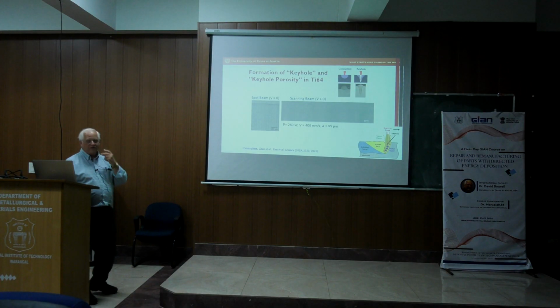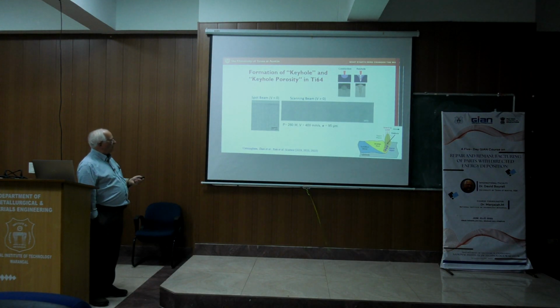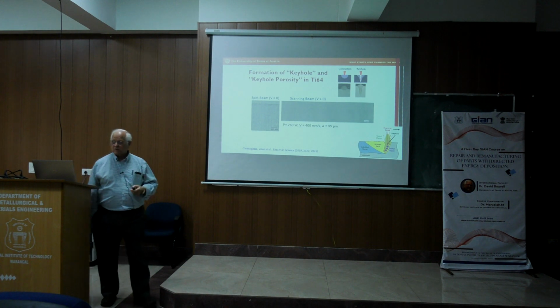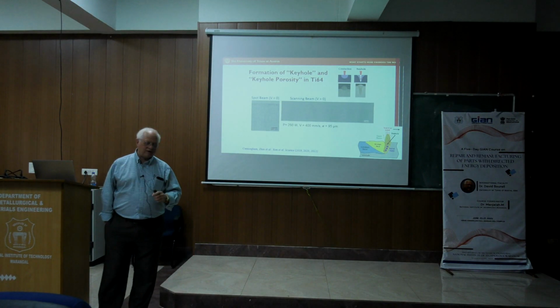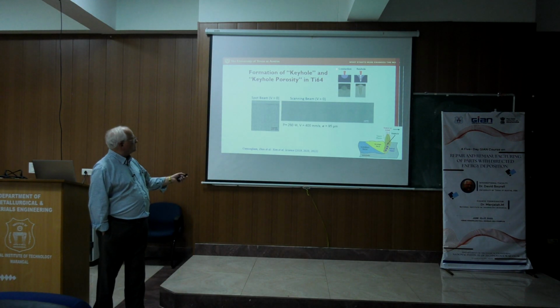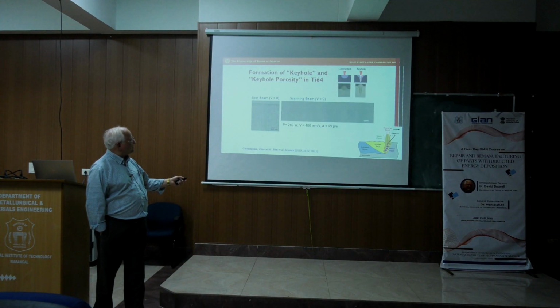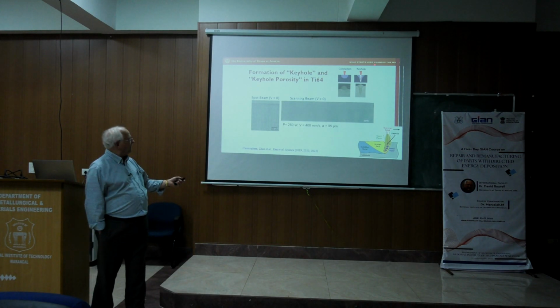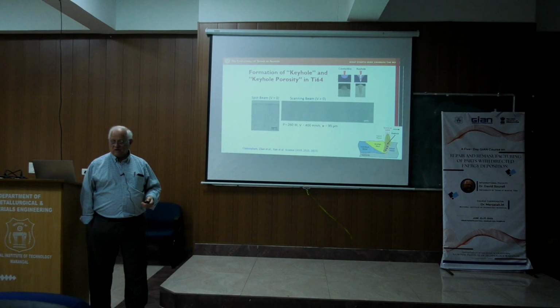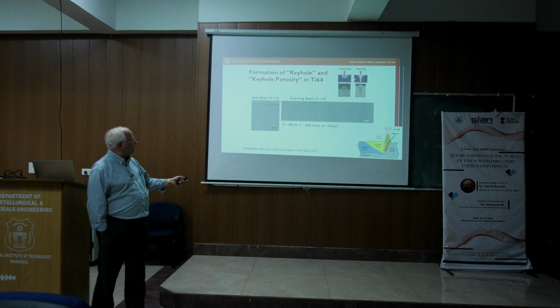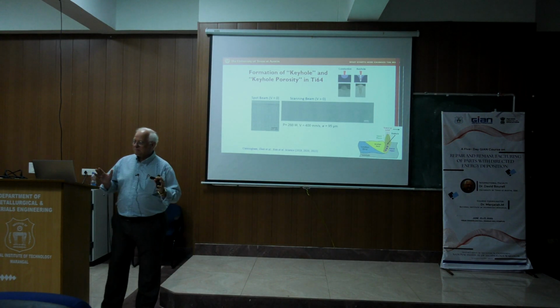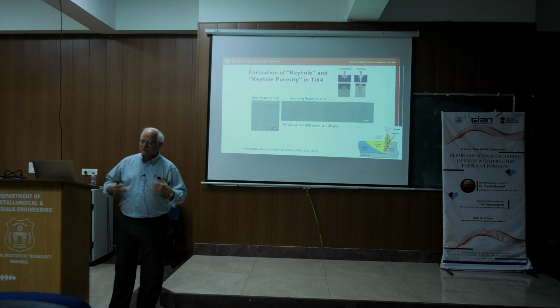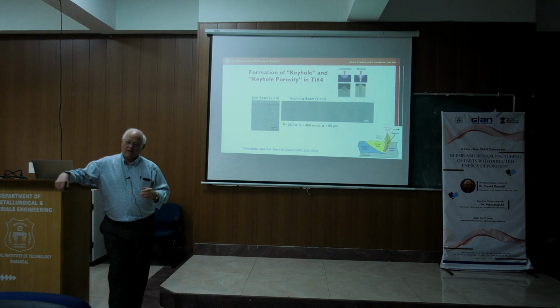Okay, here's a movie of how keyhole porosity forms. If you're familiar with laser welding or laser manufacturing, forming a keyhole is common. This shows a keyhole where the white space is basically nothing, the light gray is molten metal, and the dark area is the parent metal. Keyholing is not always a bad thing. It is in additive manufacturing, but in laser manufacturing it's not necessarily bad.